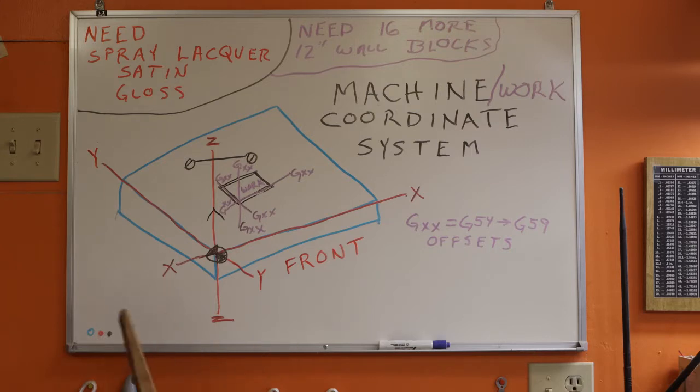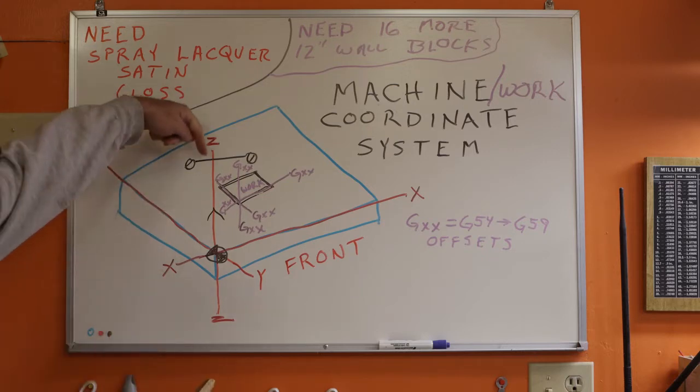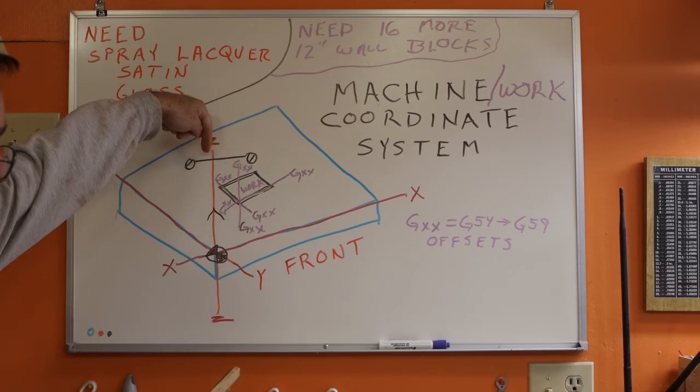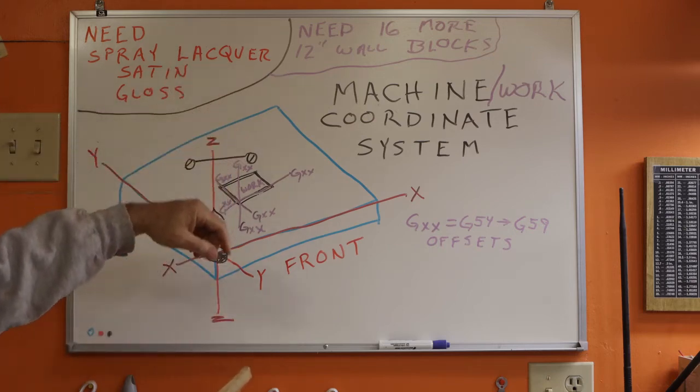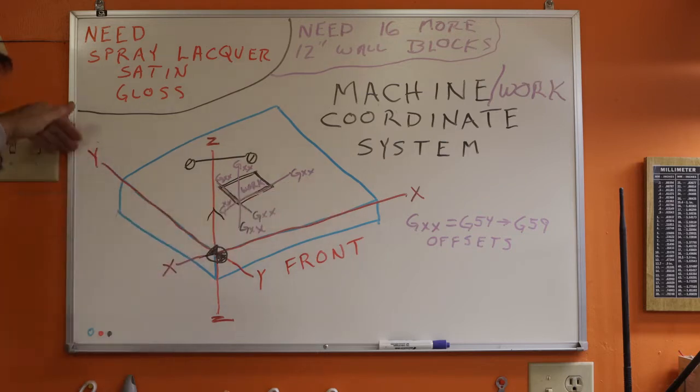That's when you home out the machine and it all goes to X, Y, Z, 0. That's when the spindle is going to be at the very top, as high as the spindle can go, and all the way over to these limits over here. Some machines have limit switches, which I'll explain in a couple of minutes, and I'll show you how that works.